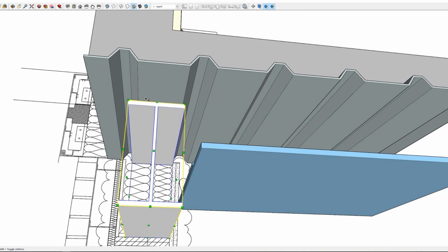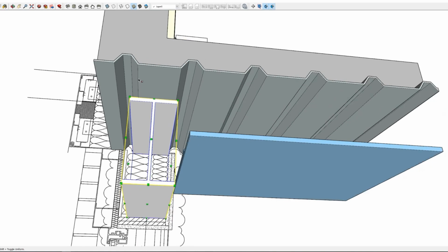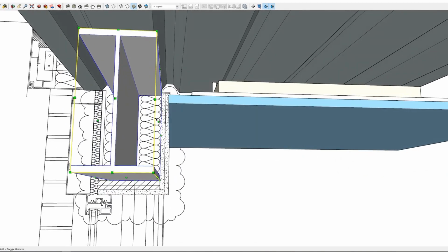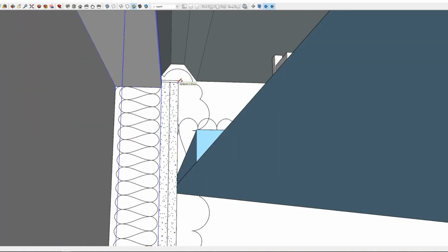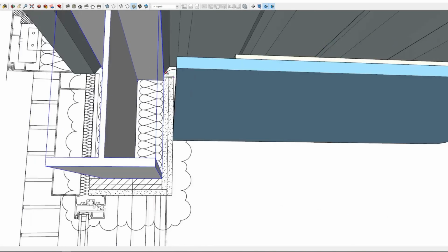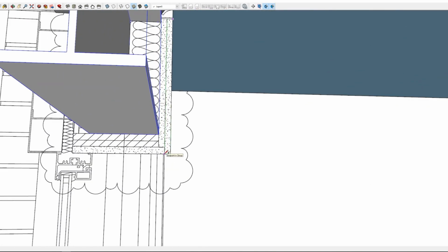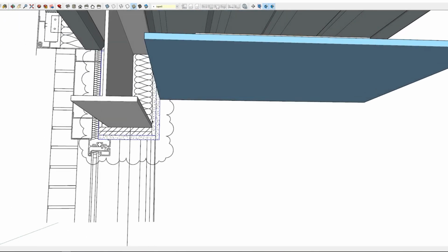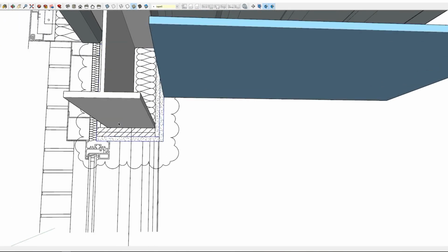And you can see there that the flat part of the wrinkly deck, the majority of that's on the head of the steel. That's then boxed in, and your 2 layers of plasterboard give you I think it's an hour or 90 minutes fire rating.